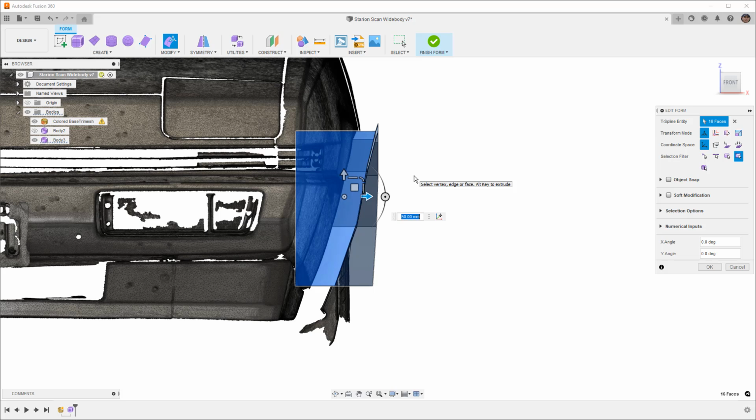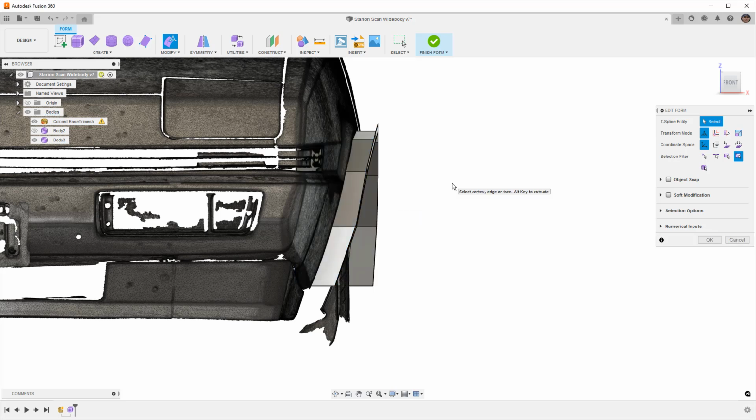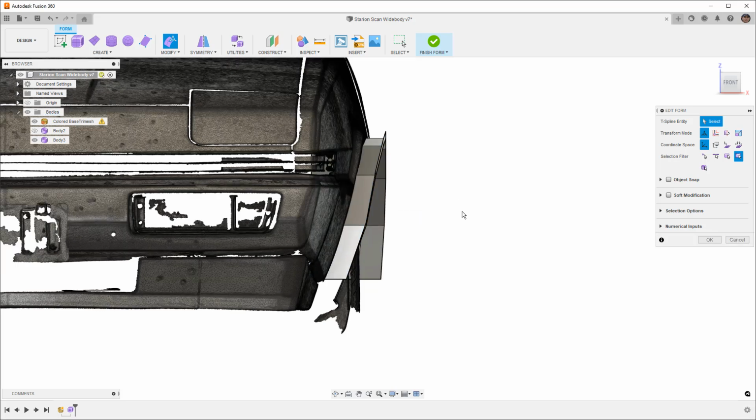My hope is to run probably a 245 on the front. So going from a 215, which is what I have now, the stock wide body cars had 205s on the front. Going an extra 50 millimeters will take me to 265, making no other changes to the back spacing of the rim. So a bit more than I want, but again, for the purposes of the video, we're going to play around with these shapes, and making something a bit more extreme is obviously going to look a bit better.